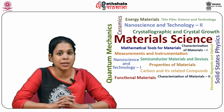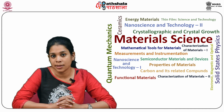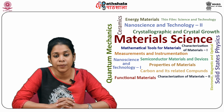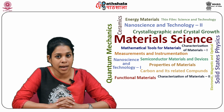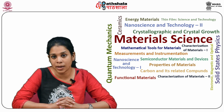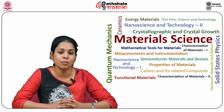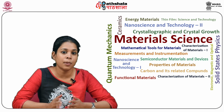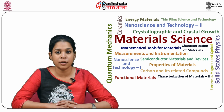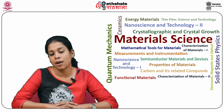So the compounds like Y2O3, that is yttrium oxide, next is hafnium oxide, that is HfO2, silicon dioxide SiO2, aluminium oxide, that is Al2O3, are far more insulating and have conductivities in the range of 10 to the power minus 5 to 10 to the power minus 14 per ohm per centimeter in the temperature range 400 to 1000 Kelvin.